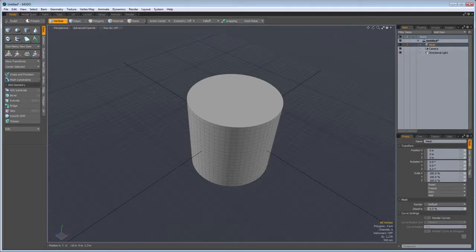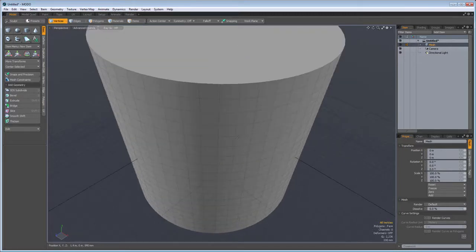So let's just select the vertices component. And you see if I move my mouse pointer over the vertices of my object that they start to highlight. And the same is true if I select Edges mode, see the edges highlighting, or Polygon mode. You see the polygons highlighting. And if I left click, I can select the polygon. And notice that it's not necessary to deselect a component to select another component.